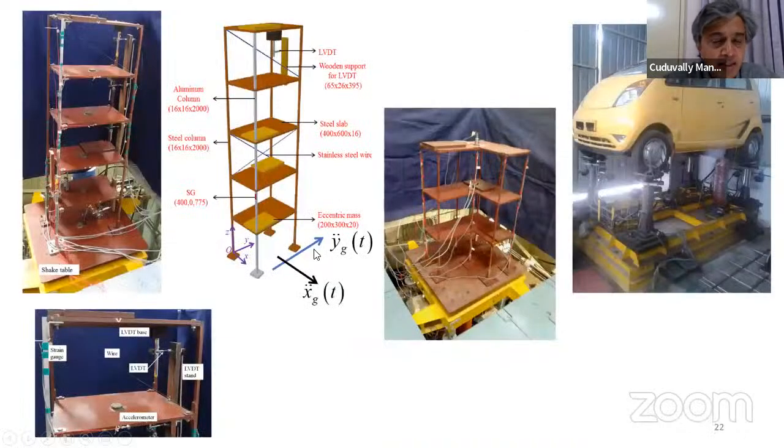So to implement that, we considered a family of systems. We began by considering a fairly, conceptually difficult system, which is a 5-story frame, which is bending-torsion coupled. One of the columns is aluminum and the other 3 are steel, and the masses are eccentrically placed on the slab. You see here diagonally there are blue lines. They are all wires, and we tested this on a multi-axis shake table that we have. We subjected it to biaxial support motion like this.